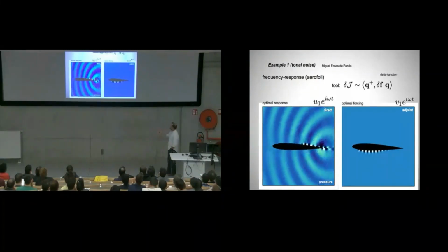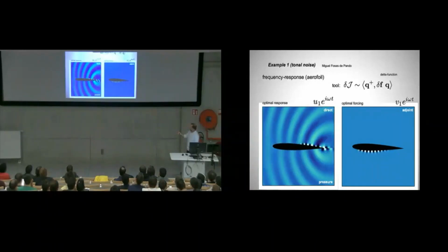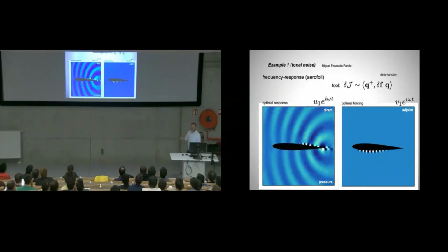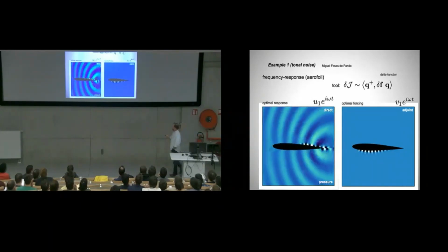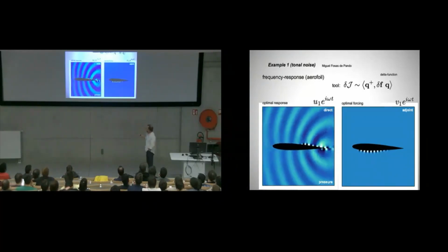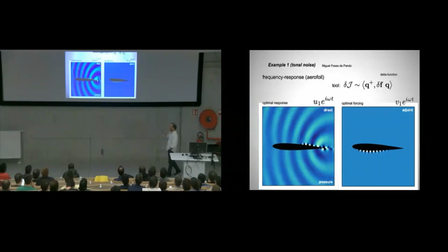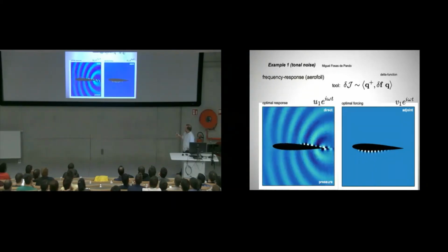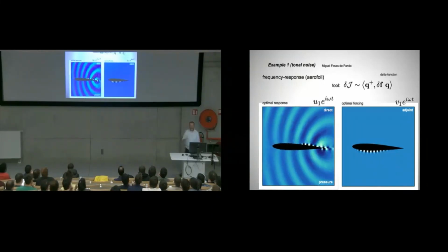Okay, so disturbing this one, people have tried to put little bumps up here to disturb that boundary layer instability up there. Did not make a difference at all in terms of making it more quiet. Okay, sometimes it even made it louder. Okay, but then there was a long time ago a Japanese technical report that never made it into the main literature. They put a wire and just traversed with the wire from here all the way to there and down on the bottom. And when they came to this spot here, suddenly the airplane went totally quiet.